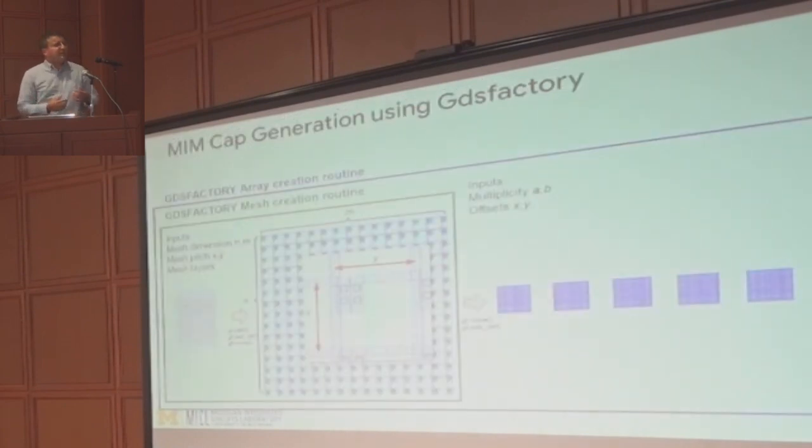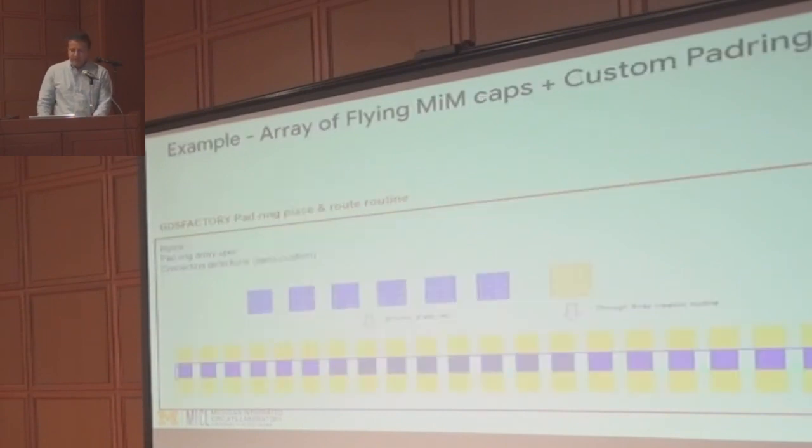As we started coding that, we started making these APIs that basically take X and Y dimensions, pitches, and layers, and it dumps an array of caps. That's very useful for applying caps, for instance, for a DC-DC converter, right? And so on. Iteratively, we started making these APIs that we can reuse across different technologies, but also generators. And we were able to put everything within the pads, which are very relevant.